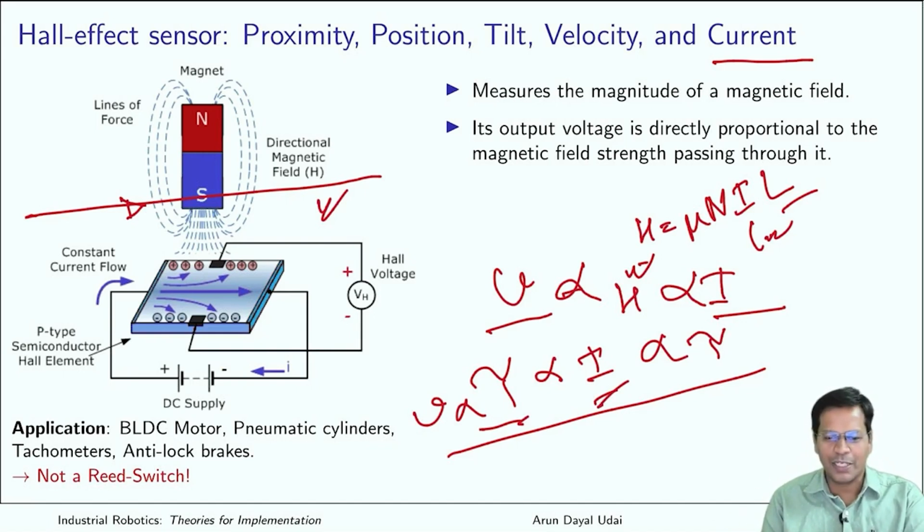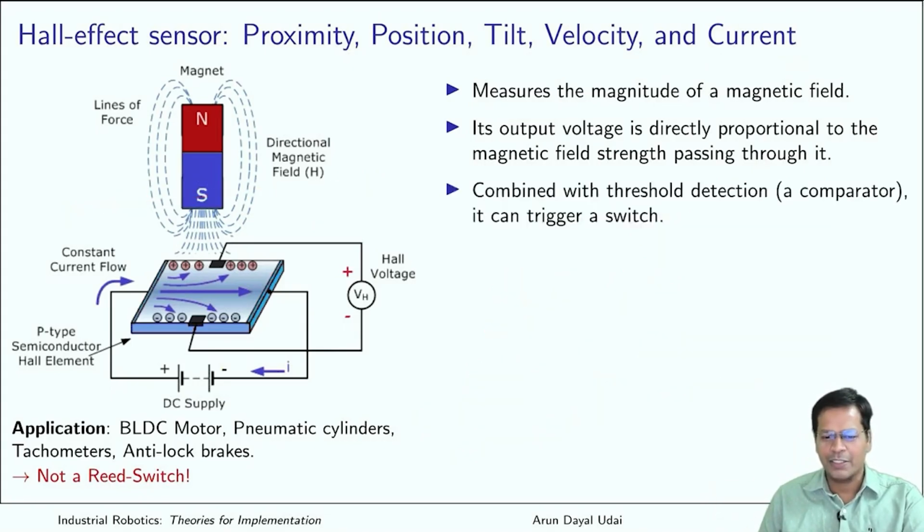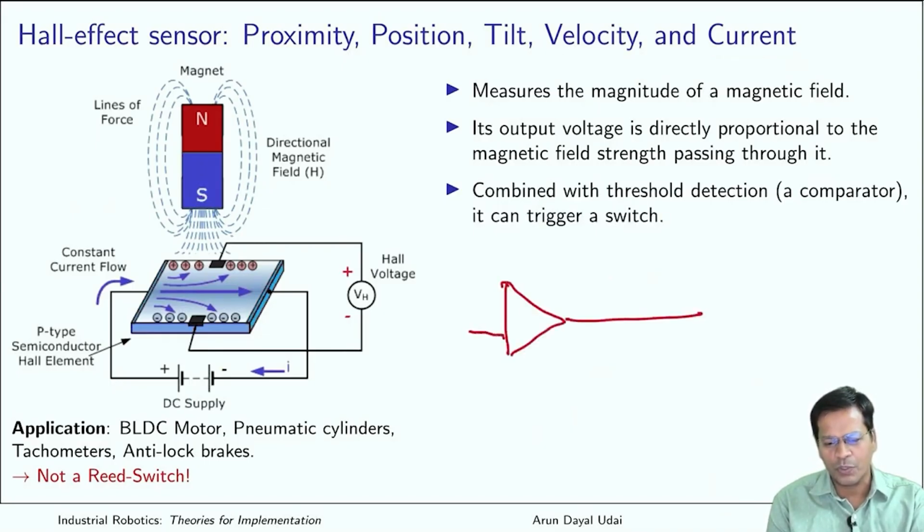These are a few things that you can measure. For other things you have to make some arrangement on top of it. I'll explain how to do it here. If this voltage comes here, you have a comparator that can give you output. There is a voltage level set here, again, like a potentiometer we can set it. This is the level with which I want to compare.